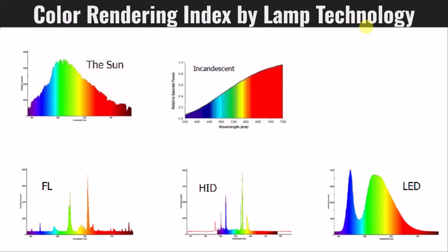Incandescent: we went from sun to fire to incandescent light bulbs as our first artificial source of light to create interior spaces that were controllable light. And this was not horrible. It's almost kind of the opposite curve in a way, so that you got really good color rendering with incandescent lamps in the warmer colors and less so in the cool colors.